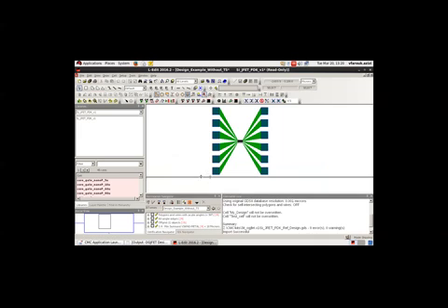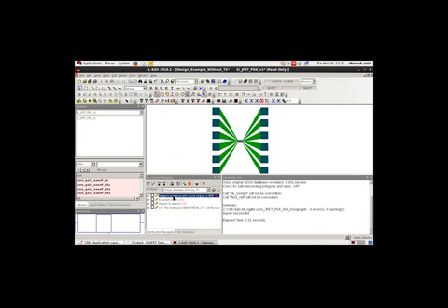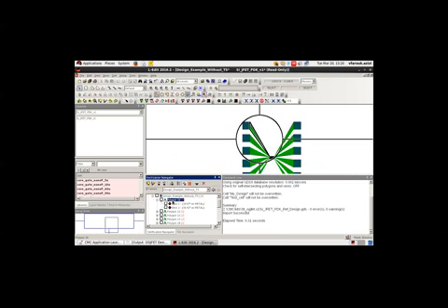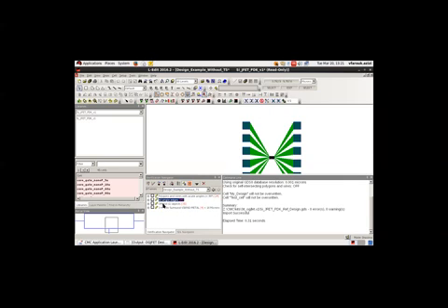Okay, so the DRC results are listed here. Some of these errors or warnings that you have received are not based on the design rules. So for example, here, this error talks about an angle that is 30 degrees, and an angle for the polygon that is 34, which is not one of our design rules. So you don't have to worry about this error, this one or this one.